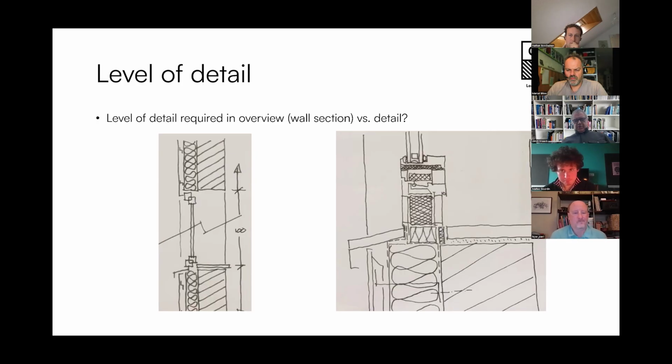If you then go into a full BIM-based project or something, you may end up in a three-dimensional sketch, copying the system suppliers' details into your details. And when you go this route, you need to be aware that you're then telling your contractor, "I want this system," which is not what you want if you want to find the best price, because they may come with different alternatives.